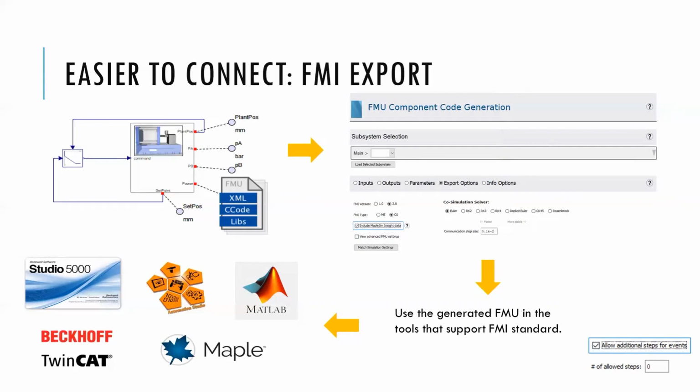And a lot of this for us has been a lot of tools in the sort of automation or PLC programming world, where you've got your PLC, you program your control code, and what you want to do is test it before you actually either build the machine or before you shut down a customer's line to investigate a problem. And so you run it against a MapleSim model that can replicate the dynamics that are going on in the actual physical machine and allow you to do testing and iterations on that control algorithm before needing, again, to build that machine or shut down a line.